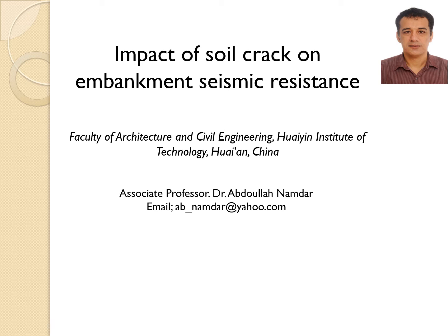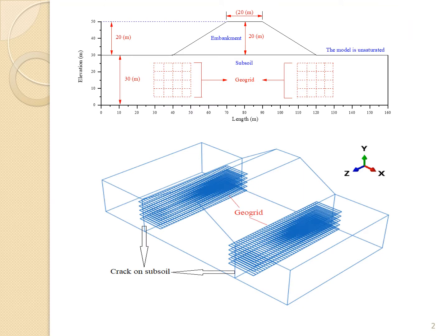I would like to present a numerical analysis. In this investigation, I use the nonlinear finite element method, called Abaqus software. In this software, a seismic load, which is selected from the literature and collected at an earthquake station, is applied to the model. One type of soil, unsaturated soil, is used to simulate the embankment and subsoil.